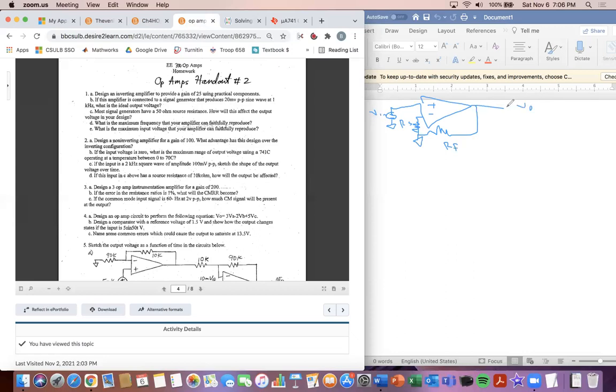And so now that we have those, we have this with a gain of 100. So gain of 100, remember our equation, V out equals 1 plus RF over RS times V input, and RF over RS must equal 99, because 99 plus 1 is going to be 100 for a gain, because this is our gain right here, 1 plus RF over RS. Okay, so 1 plus our value here, I'm going to make 99K be our RF, and RS is going to equal 1K ohm.